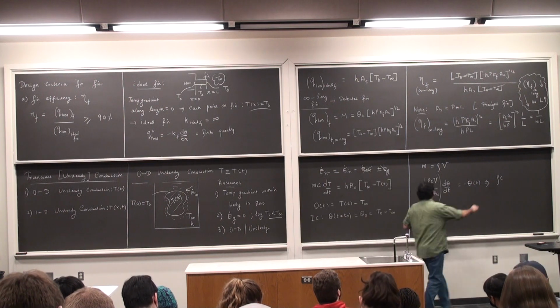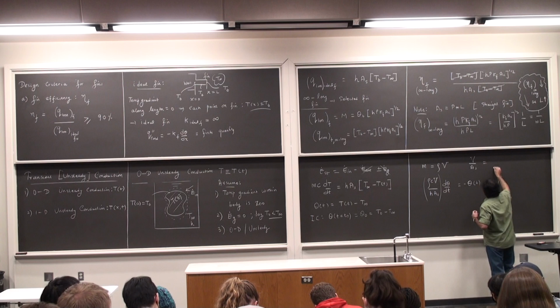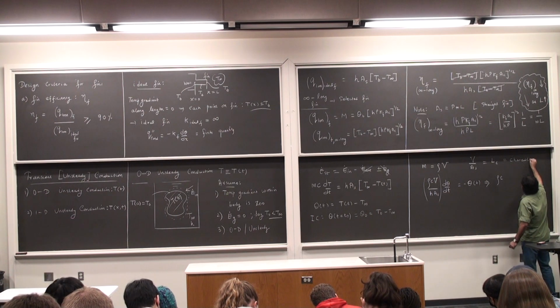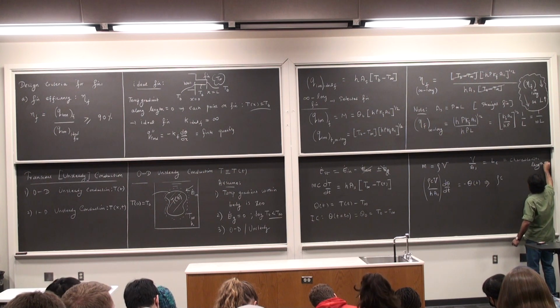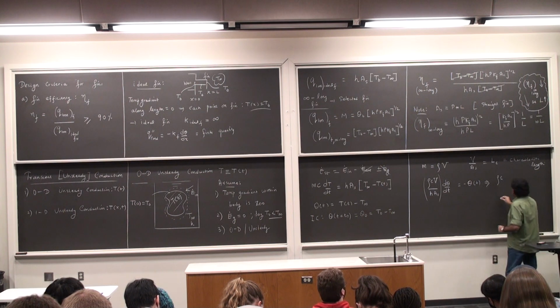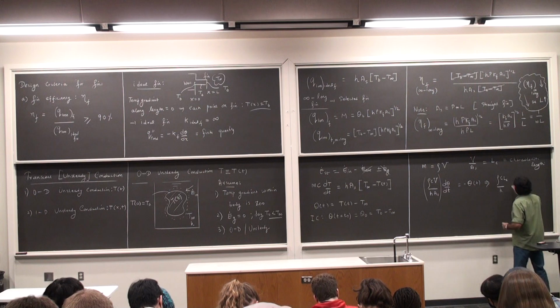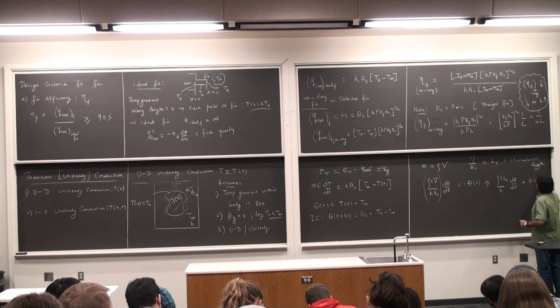So I'm going to say that volume by the surface area is L_c. Characteristic length. So this is going to be rho c L_c by h, d theta by dt plus theta is equal to 0.